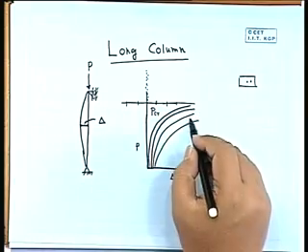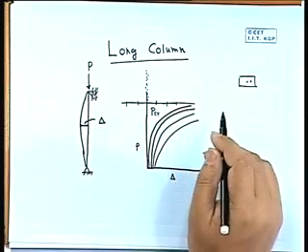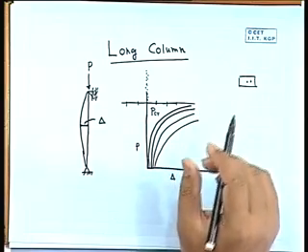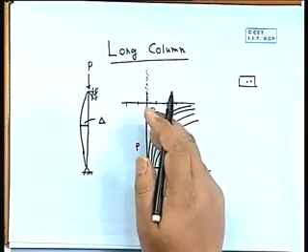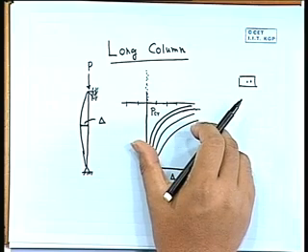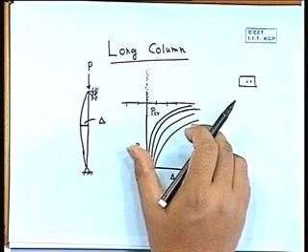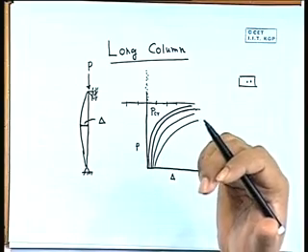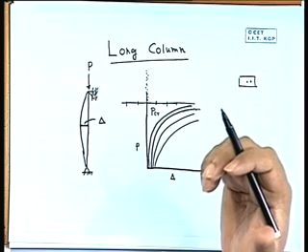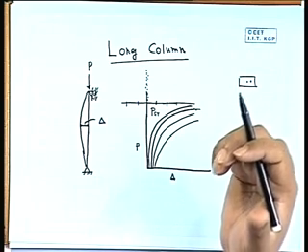Now, in our elementary theory, we assume our deformation is very small, we are not taking it as a large deformation problem. When the deformation is large, we can get only a very small part of the curve. Because at this level the curve will try to become flat, if we want to go in this range, there will be huge deformation. So if we want to go to that range, we have to take the effect of large deformation, right. So the whole problem will be a nonlinear problem, and solution of a nonlinear problem is quite difficult.